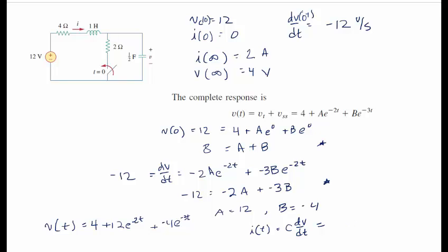You can obtain the other quantities of interest in this, like we had written a KCL equation here. We have V over R here, and an I here that's C dv dt. So you can go through and get the other quantities of interest in this circuit too. Maybe we should do this I right here.